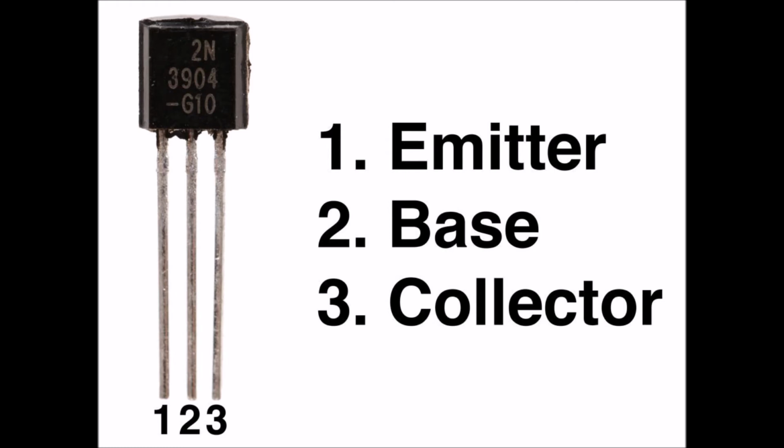This is a PNP transistor. That is, a PNP transistor is on when its base is pulled low relative to the emitter. In a PNP transistor, the emitter base region is forward biased, so holes are injected into the base as minority carriers. Saturation. Saturation in electronics refers to a maximum beyond which the system becomes unstable. If a device reaches its maximum voltage when a certain amount of current is given as input, then that amount of current is known as saturation current, and for voltage it's vice versa.